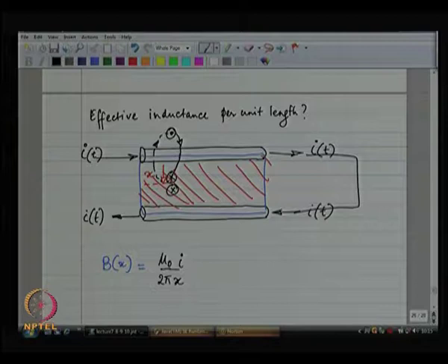This is the situation that we are going to talk about, and why we are talking about this as a special situation is because when I have a wire over a conducting ground plane, then an image of the wire is going to be beneath the ground plane. So, this situation is routinely going to arise in our integrated circuit. That is why we are specially talking about it.